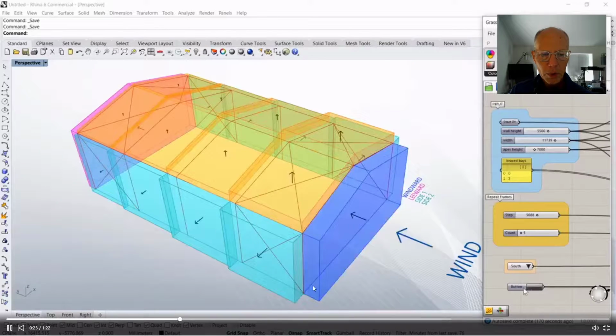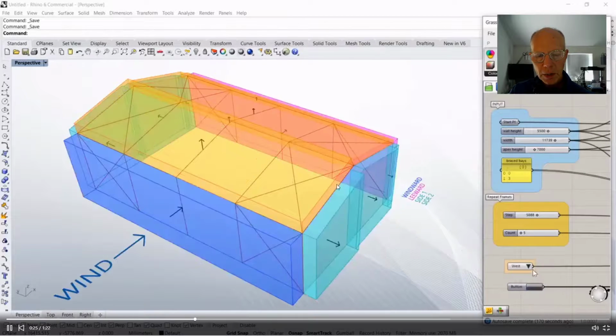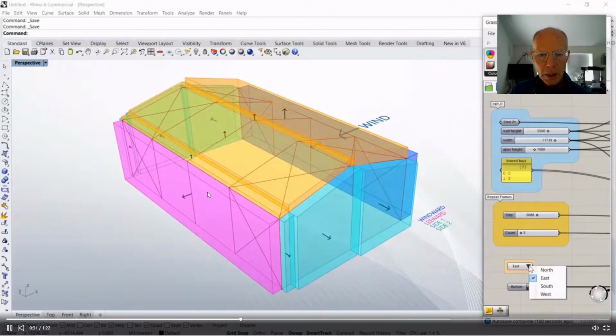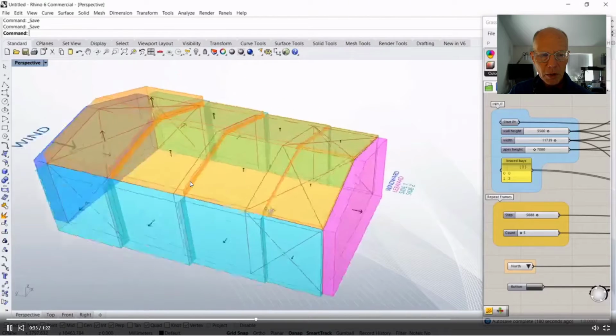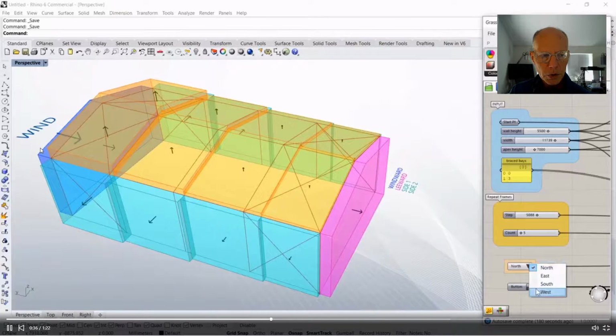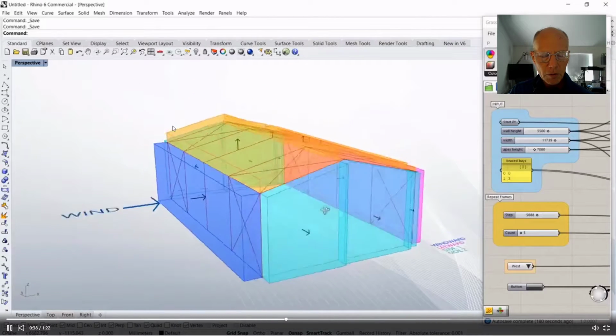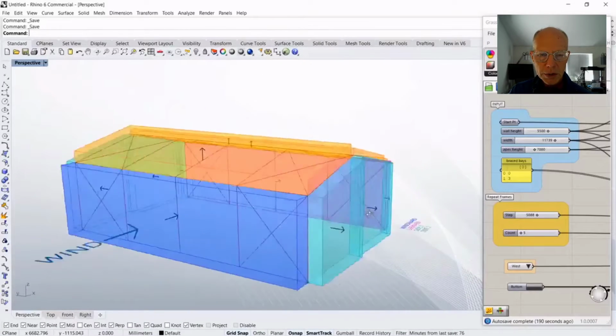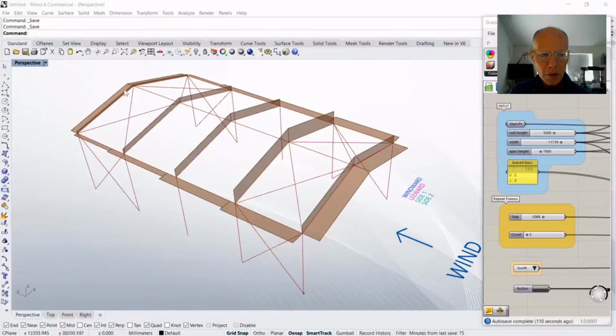More to the point, here we have the idea of a positive pressure wind load, and then we see a lot of surfaces that are pulling out, which actually have negative pressures on them. As a matter of fact, in predominant wind forces, a lot of the surfaces of the building have negative pressure loads on them. So I had mentioned in the last lecture how you'd see positive and negative values.